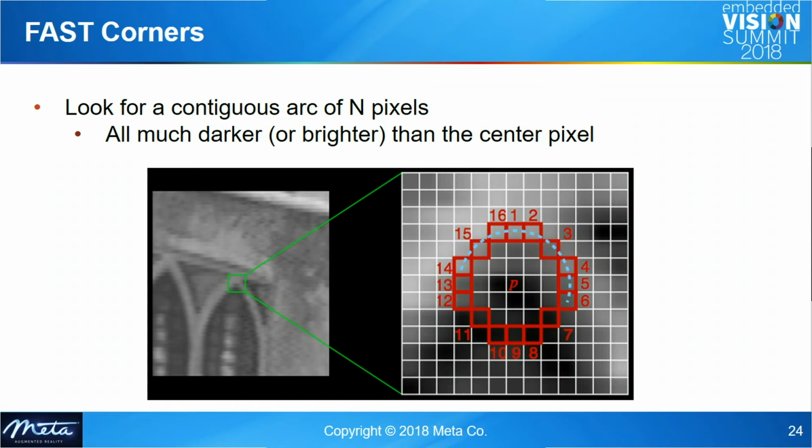First of all, we want to find good points for SLAM that are easy to find from different camera poses, and maybe the most traditional computer vision algorithm for this is the Harris corners. These days, FAST is widely used for corner detection.